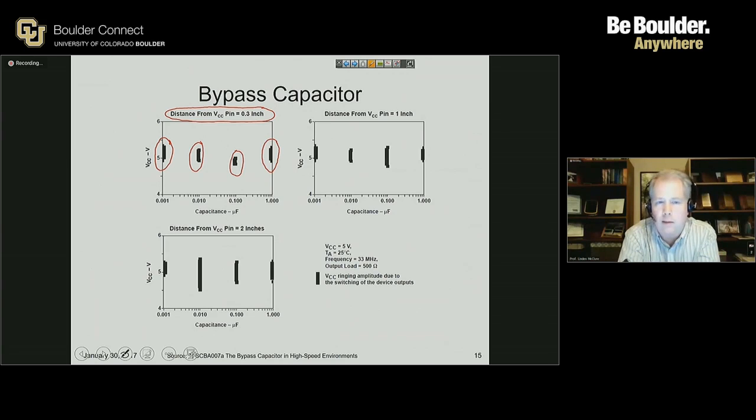The reason for this is that the capacitor with the leads that have to be soldered through the board will necessarily have additional loop area as a function of the current having to go up the lead into the capacitor, down the lead to get out of the capacitor. If I use a surface mount chip, I have removed that additional path for the current to flow, and the surface mount capacitor will give me a lower inductance for the same capacitance size.